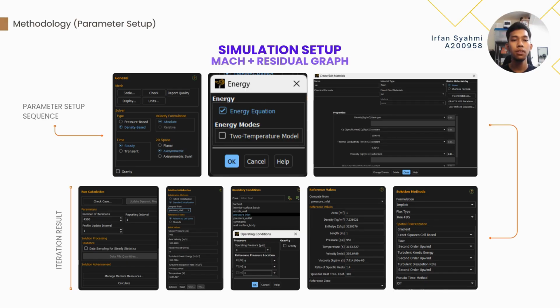Since our reference rocket burns refined kerosene and liquid oxygen, the exhaust is extremely hot and fast. To save computer processing time and avoid calculating complex chemical reactions, we model the fluid simply as an ideal gas. This accurately captures how the gas density changes as it rapidly speeds up.